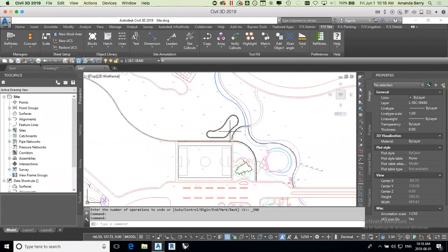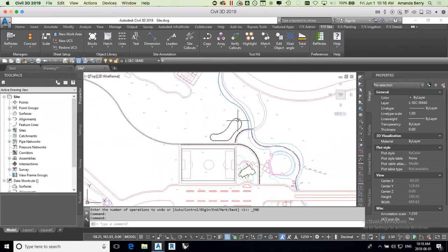So we're here in civil, and the first place that we're going to look is the tool space over here. This is your main hub of AutoCAD Civil if you haven't been here before. You have two main areas that I used as a landscape architect doing grading. The first one is the prospector, and the prospector is basically where all the physical objects lie, all the information on everything that is actually drawn in the plan and exists in the plan.